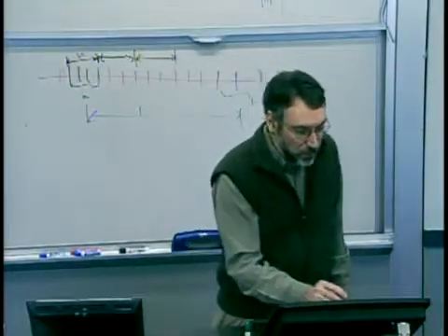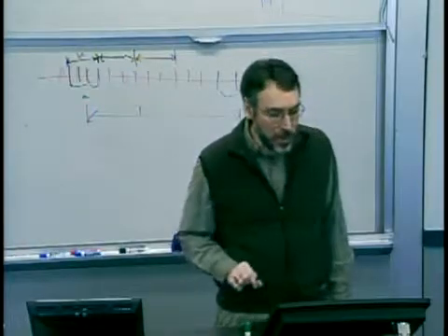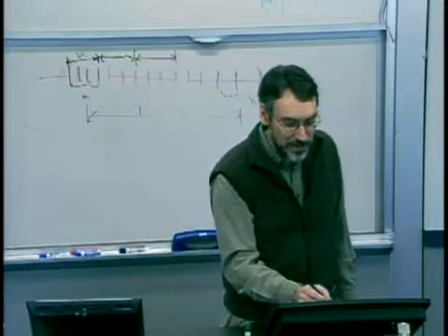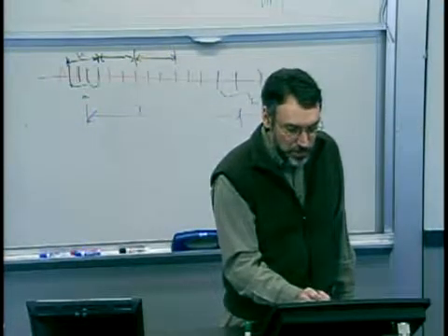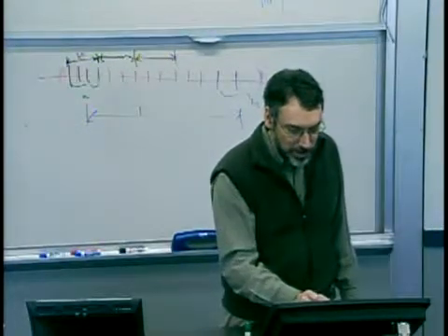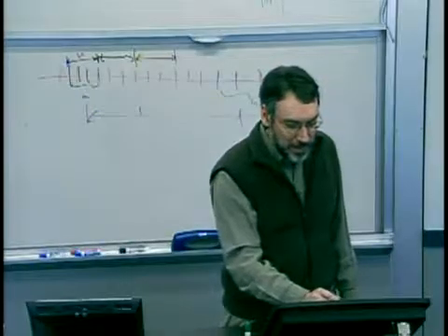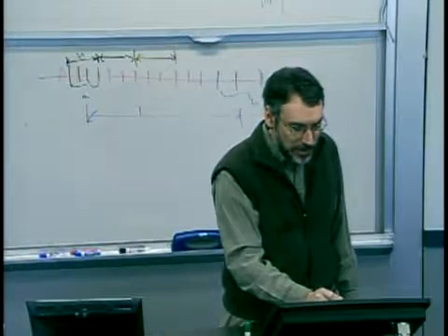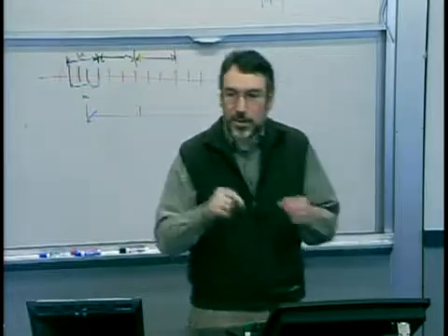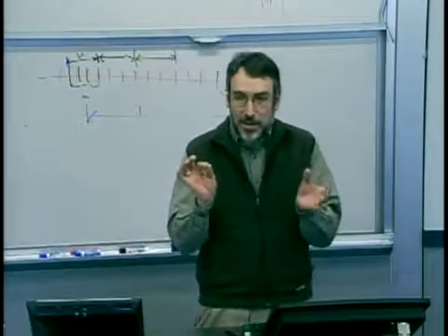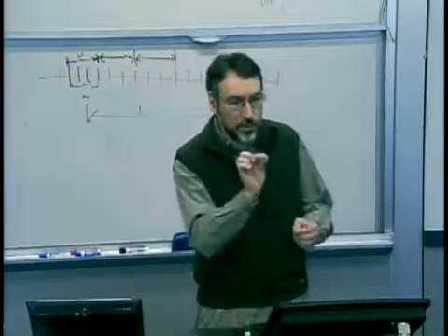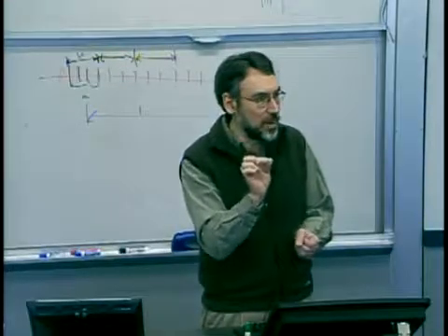One thing that's nice is if you look at the expectation of that quality loss function, and just go through and do a little bit of the basic expectation math on that, where you factor out x minus x bar, do that squaring, and then relate components of the expansion, what you get is one component that is clearly related to your variance in the process, and another component that is clearly related to your mistargeting or deviation from the mean.